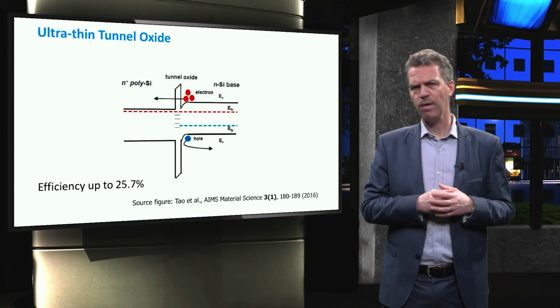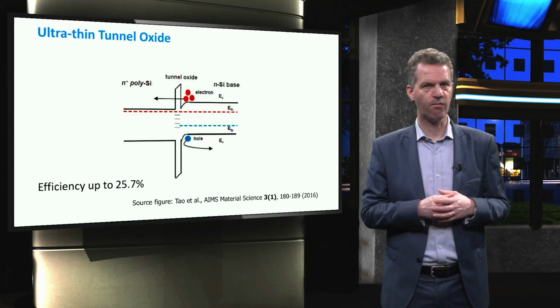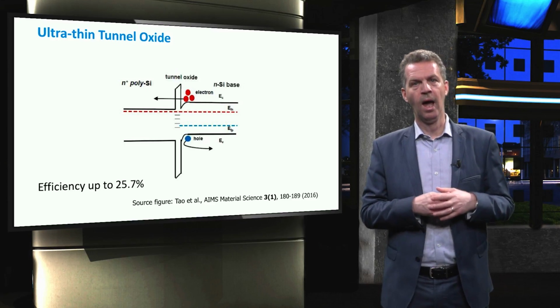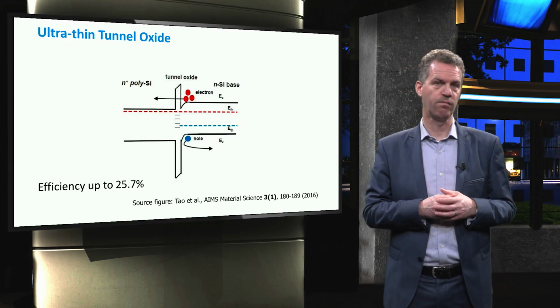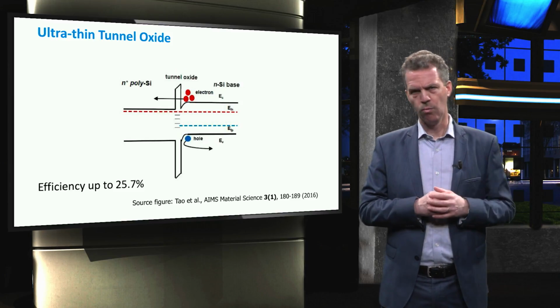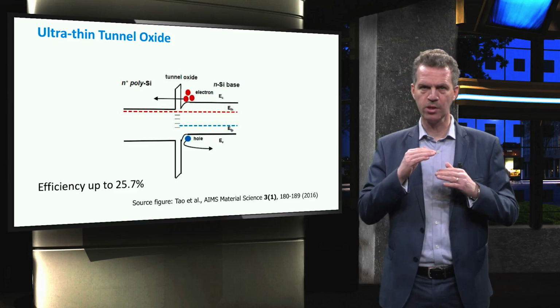An efficiency of up to 25.7% has been reported by ISE Fraunhofer Research Institute in 2017 with this concept, and it is still developed further. This is the world record efficiency for a monocrystalline silicon solar cell with both sides contacted. Both the PERC solar cell family and the TOPCon solar cells have improved the conversion efficiency of the cell itself by implementing optimal design features.